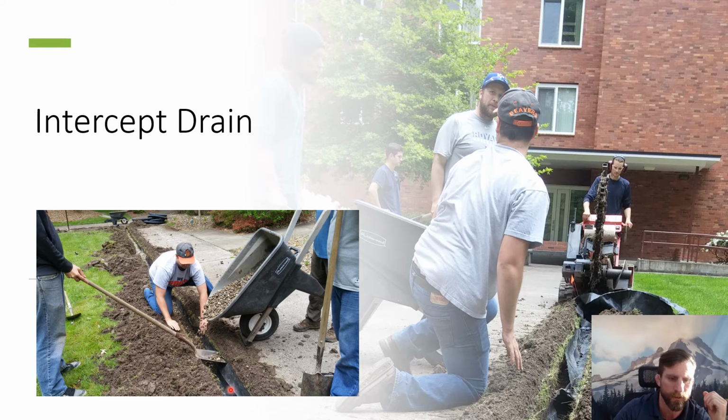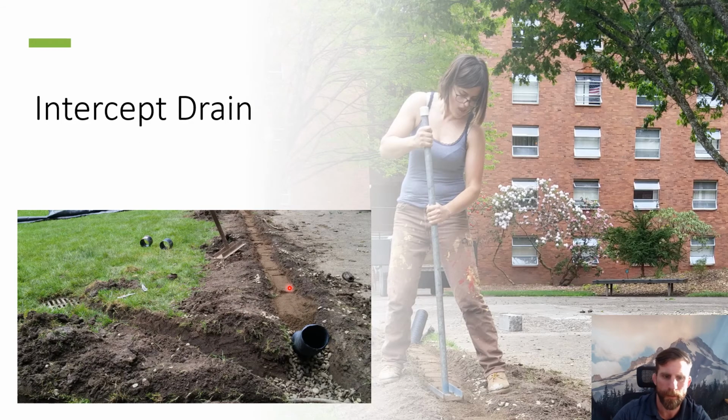Okay, so you've got the drain tile with fine gravel over it. You've got the geotextile fabric in there to stop the native soil from getting into the fine gravel in the drain tile. Okay, and then in the next picture here you see we're putting sand over top of the fine gravel or stone here to provide a media that can hold just a little bit of water to grow some plants, some grass, but still have very rapid drainage.